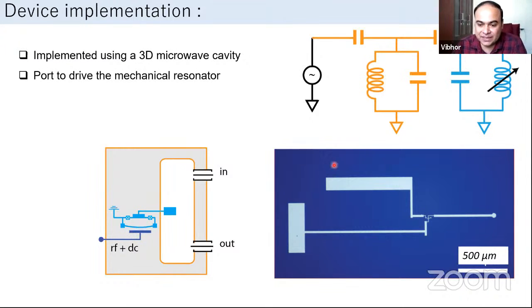Okay. So this is how the patterned device looks on a silicon nitride substrate. This tiny electrode that you see here, that's the capacitor, which is going to shunt this SQUID inductance. The tiny plus-like shape that you see here, that is the SQUID loop. And inside we have these Josephson junctions and the suspended mechanical oscillator. The other two electrodes we have here are just for performing input and output and applying gate voltages if needed.